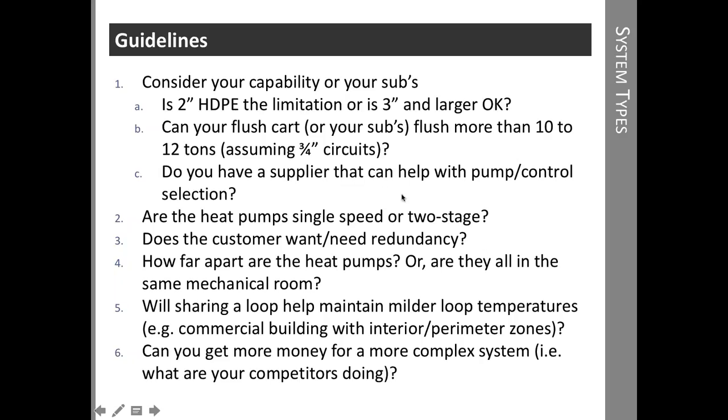Pump control, selection, all that kind of thing, Enertech can help you with that. Are the heat pumps single speed or 2-stage? A 2-stage heat pump benefits more from a variable speed pump, of course. Does the customer want redundancy? We have to look at that on a central system.